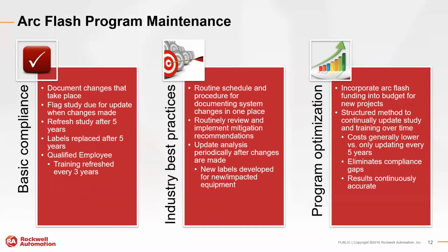You should refresh the arc flash study after 5 years have passed. Per that guideline I had in the last slide from NFPA 70E, perform refresher training for your qualified employees and training in general after 3 years.